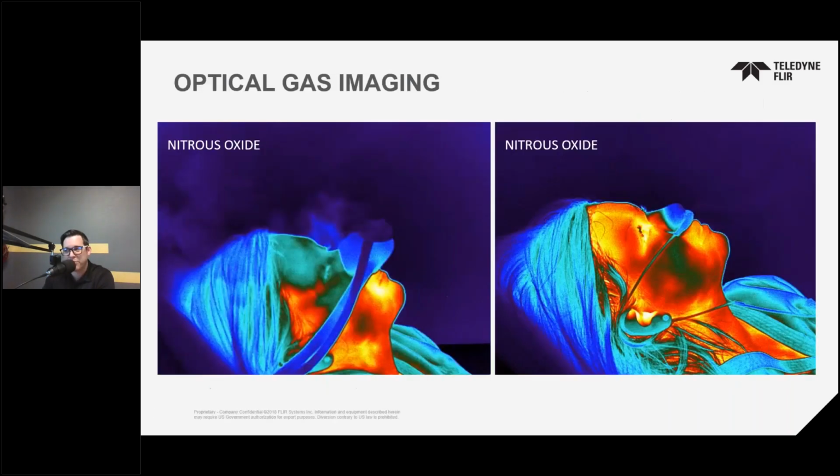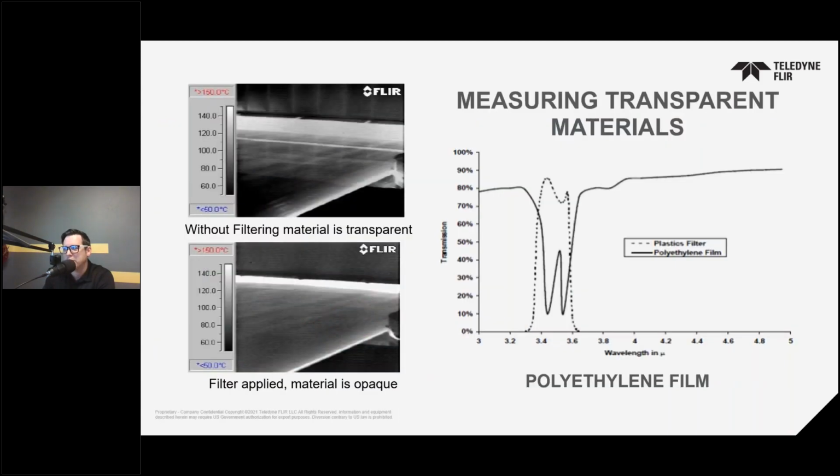Oh, and I will say that, similar to putting a black body or some calibrated temperature source on the other side, it's very similar when you want to see the transmission of even an IR window, or what the transmission of an air path looks like if you're looking at some distance out in the open air. If you're out in the field and you want to see something that's, let's say, 1,000 feet away, or 1,000 meters away, you could put a known temperature source at the far end, as long as it's large enough that you've got a decent number of pixels on it. You could then measure, because you know what that temperature value actually is because it's a calibrated source, and tell what that transmission path looks like. Same with this material if you're trying to make it opaque. Same with an IR window if you want to know how much transmission loss is occurring when you're looking into that chamber. You can do it that way as well.